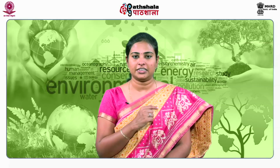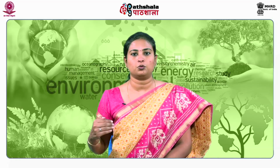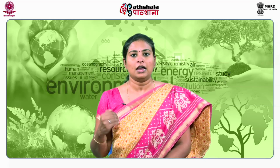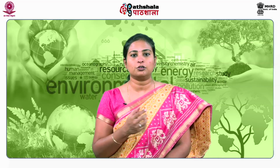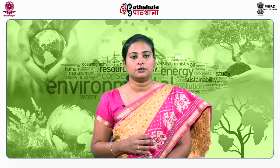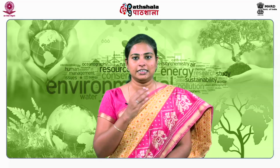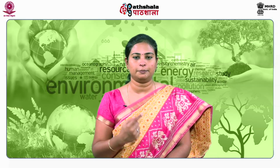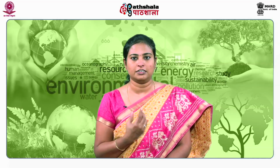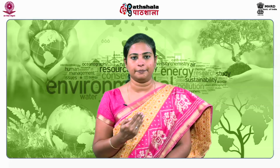Now, the reed beds have an inlet zone of crushed stones to distribute the wastewater or the leachate uniformly over the bed, with an outlet zone of compacted stone to collect the effluent on the other side. The leachate that enters the inlet will move slowly through the bed following a horizontal path. As the leachate flows, oxygen circulates into the bed. Then aerobic bacteria surrounding the rhizomes of the reeds will start consuming the organic substances and oxidize them.